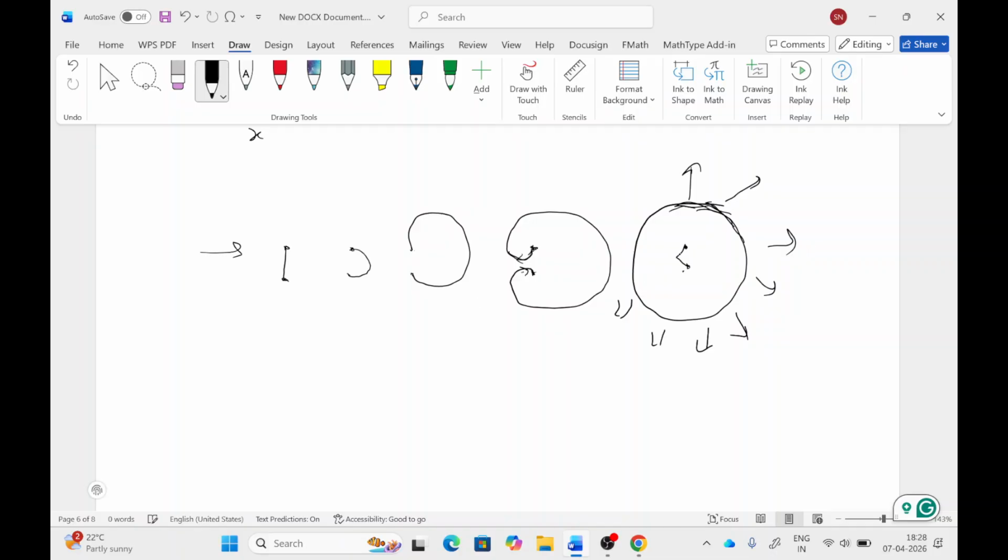With time, this dislocation line further gets straightened out like this, and if further stress is applied continuously, this process will continue and generate more and more dislocation loops. As more and more dislocation loops are generated, they will pile up at grain boundaries.